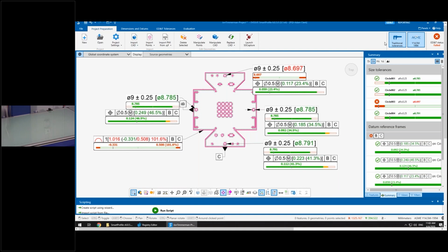So for the adaptive setting, what determines the number we should use? There actually isn't a number to know what you should use, because each part is going to be measured differently. Whether you're using stainless steel, rubber O-rings like we had here, or even cast iron, all of that is going to reflect differently. What adaptive is doing, in essence, is shifting the way it grabs the measurement data from the image that was taken.